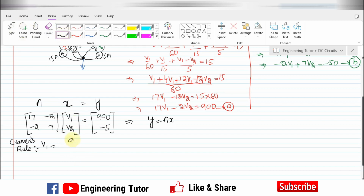Okay, so this is 900, minus 5, and similarly the other column will remain the same, this is 7, and taking the determinant and then dividing the overall over the determinant of this A matrix. So the matrix is basically 17, minus 2 and 7, and the determinant of this matrix. So after finding all the values here and finding the determinant, we have found out that the value of v1 is 60 volts.